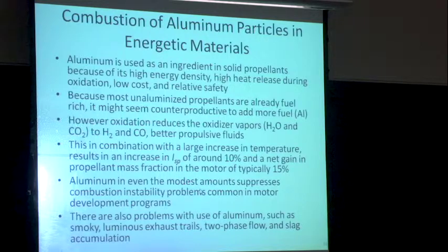It also can reduce combustion instabilities, but there are negative features as well. As I said, we talked about propellants being smoky. It's going to create slag, two-phase flow characteristics, drag within the flow, and it could actually even lay on the nozzle and change the characteristic dimensions of the nozzle cross-sectional area.